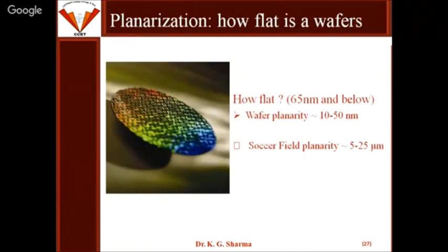When we are fabricating the transistors on the wafer or on the chip, it is also required that the wafer surface should be flat. And as the technology is advancing, we require that the surface should be more flat, because we do not want any type of hillocks formation or any type of valley formation over the chip surface. So we have to look how much flat surface we are having.